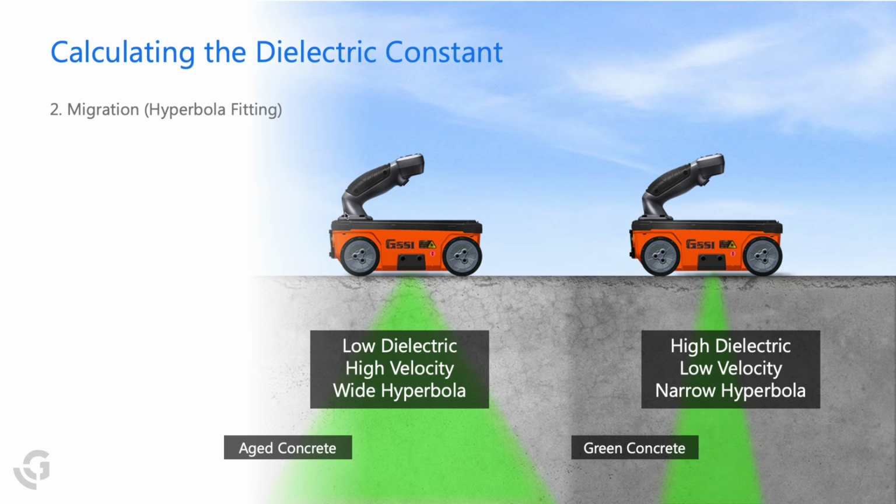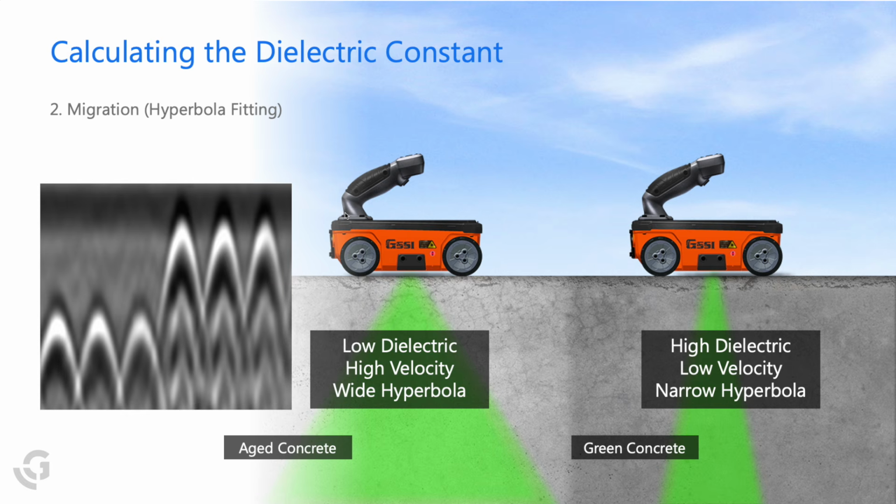To do so, we simply collect some data, produce crosshairs on the top of our hyperbola with the backup cursor and horizontal cursor. Under calibrate, we will produce this blue hyperbola on our screen. From there, we simply adjust the width of the blue hyperbola to match the contours of our data, and by doing so, we've just calibrated our system to that particular slab.